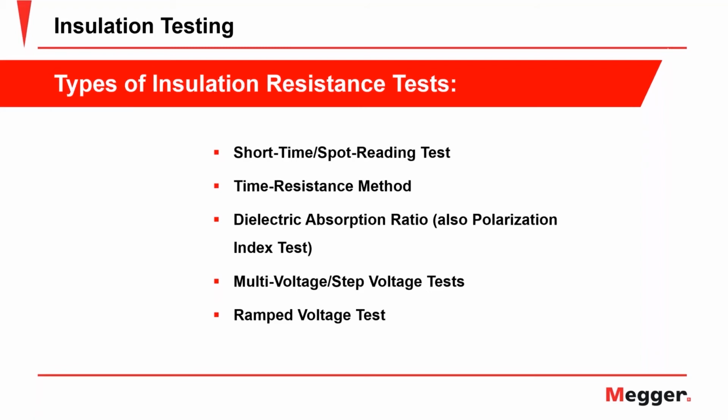And then that'll put you on home base on how to interpret what you're seeing, because insulation testers are radically different than DMMs, where generally, you see you got 122 volts or you got 1.5 amp of current flowing. There's not a whole lot of interpretation that needs to be done there, but with an insulation test, there's a lot of interpretation. Now, the various procedures, like I said, we're going to cover them next week. We're only going to touch on them this week.